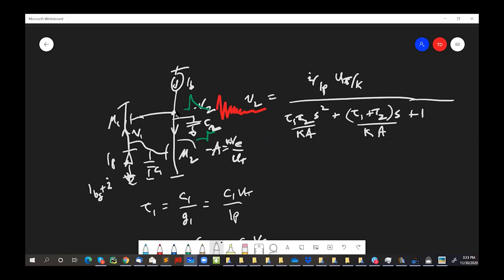Okay. So the question is how fast do you actually have to make tau 2 in order that you get this ideal response, that it really has that effect? Because you don't want to burn infinite current in IB, right? So you can answer the question now by asking what IB needs to be. In other words, what does tau 2 need to be to get Q equals 1/2? In other words, to get the response to be a nice exponential response to the output instead of ringing.